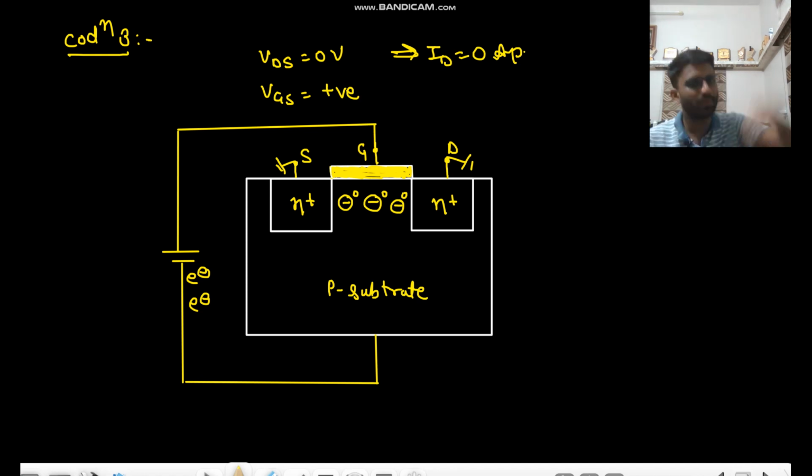The charge carrier has to go into the drain terminal, and for that there has to be some potential, be it positive or negative. If we are talking about N channel, be it depletion or enhancement, if there is no positive voltage on drain, there is no chance that the current will flow. So VDS has to be positive. So the current is 0.